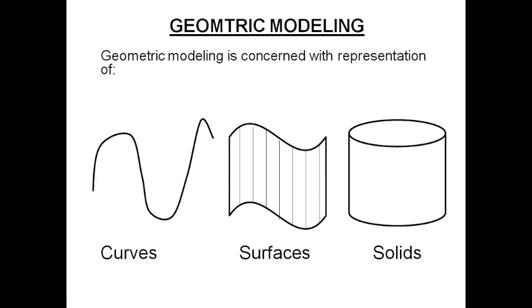representations. Let me tell you that parametric representation of curves is the most popular form of representation as far as geometric modeling software or CAD modeling software are concerned. So most of these softwares, whether it is SolidWorks, Wildfire, NX, Fusion 360, they make use of parametric curves to model their curves or to store that information about these curves.